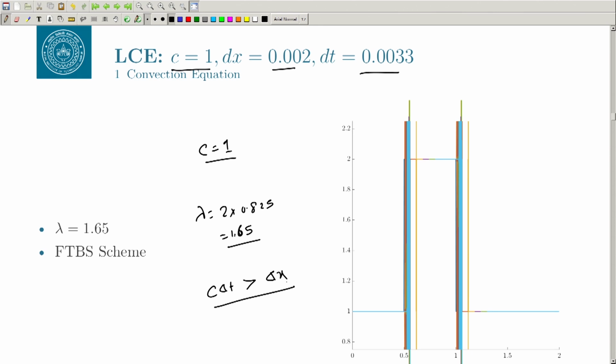When we did that, you can see quickly that our solution blew up. You can see these lines going towards infinity, a very large value. Since I have used a limit in the x and y direction, you do not see it here, but it is everywhere. And the thing that you desire, that it will convect to the right side, is not happening.